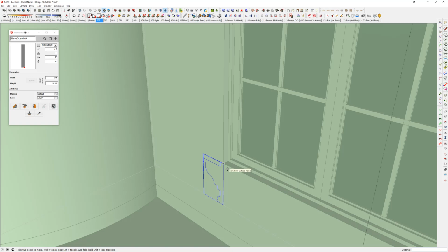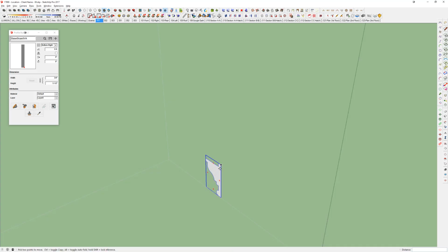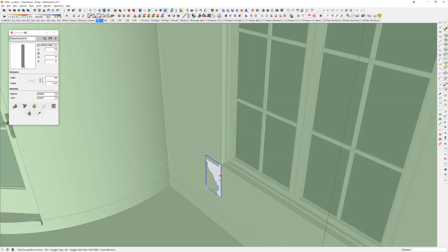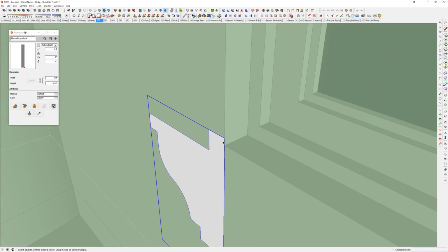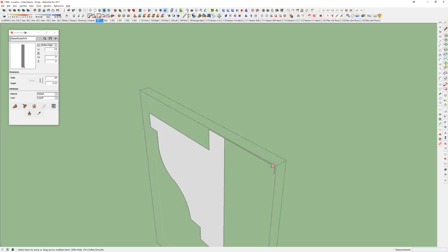The profile changes. It has a miter joint that's going to come back in, and so this one's going to be done slightly different. So I'm going to put it on the edge, and again, I'm going to move it up half an inch, and then I'm going to draw in that additional trim piece that I talked about that allows the trim to go back.